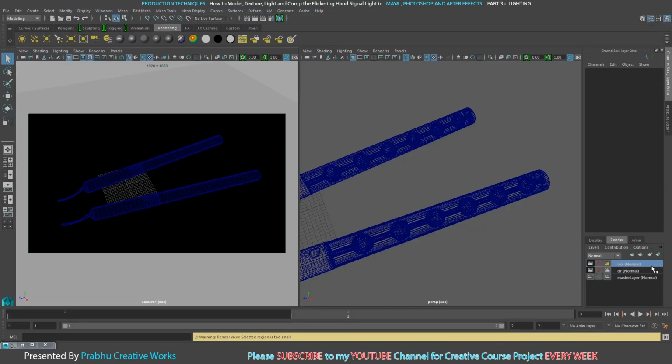Now I want to select my occlusion pass. So you will render either one or two frames. Because the occlusion in the first frame and second frame are the same, since we cannot animate our camera, we only animate the object. So you will take any one image for our occlusion pass. So select any one frame, select the camera view and click render. You want to choose the occlusion layer and click render.